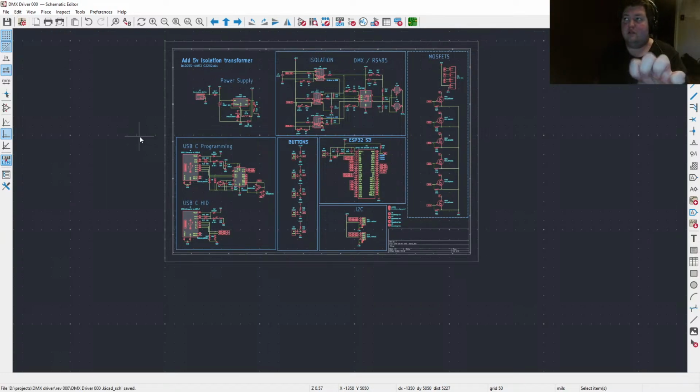But the idea for this project is this is one of two boards that I have to design. The other one is a board for motion gloves. So I would sew together a pair of gloves that have flex sensors in the fingers. And then the control board would have a spot for battery monitoring, charging, an ESP chip because everything's going to run on Wi-Fi, an accelerometer, haptic feedback, an LED indicator, probably a few buttons too.